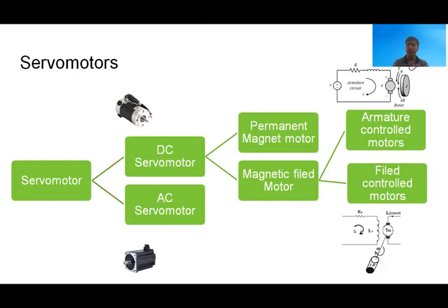The suitability of the motor for a particular operation depends on the characteristics of the motor, the purpose of the system and its operating conditions. Some features of the servo motor are useful to know to select a particular servo motor for a given application. Those characteristics are a linear relationship between speed and electrical control signals. When it is a linear relationship, it is very easy to control the servo motor.